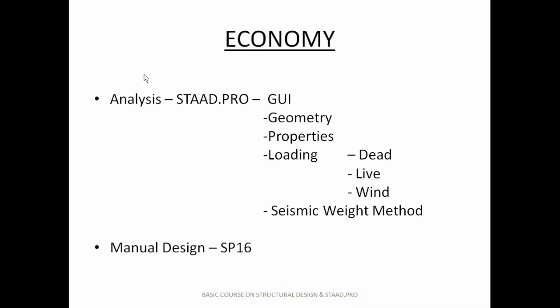STAAD is actually a matrix displacement based method. You must specify the materials, geometry and properties before analysis. That is, first design with some approximations, then analysis, then redesign. STAAD will be covered in detail. We will learn application of wind and seismic weight methods. Also, we will do a small project on steel frame design using STAAD. The best way to read the output from STAAD will also be discussed.